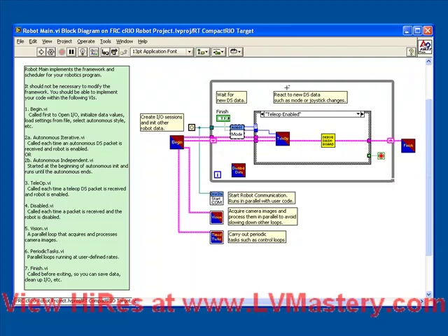And for those of you who have done testing, you may have actually observed that the time at which the Tele-Op runs is actually variable. Sometimes the delay between Tele-Op executions is as low as 5 or 10 milliseconds, and sometimes it's as long as 200 milliseconds. So if it takes on the order of a quarter of a second for your motor to stop when a limit switch is tripped, that could mean permanent damage to your robot.